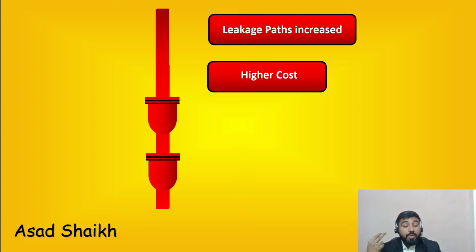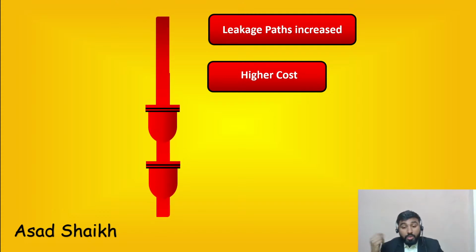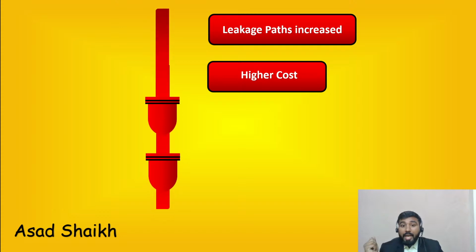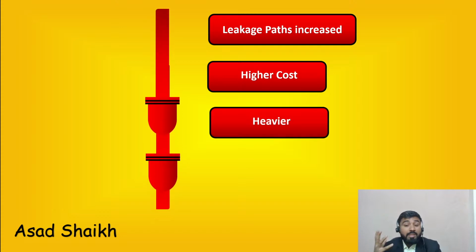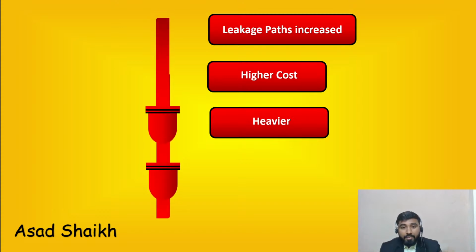Second is higher cost, because the body size is going to definitely increase, which some of you also said in the comments. That will definitely make it not a good choice, especially for your clients. And then the third thing is they are heavier, because the two ported design makes them far heavier valves compared to your regular application.